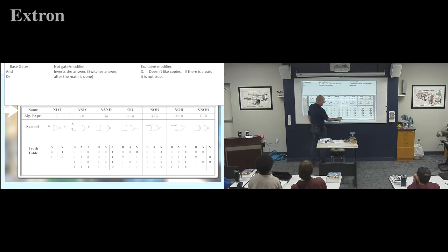So I'm going to start from the bottom again. If I have a signal at A and B, well, I do have a signal at either or, right? So it says, yep, I'll give you a signal out here. If I only have a signal at A but not at B, I'll still give you a signal out here because it's an OR gate, either or.